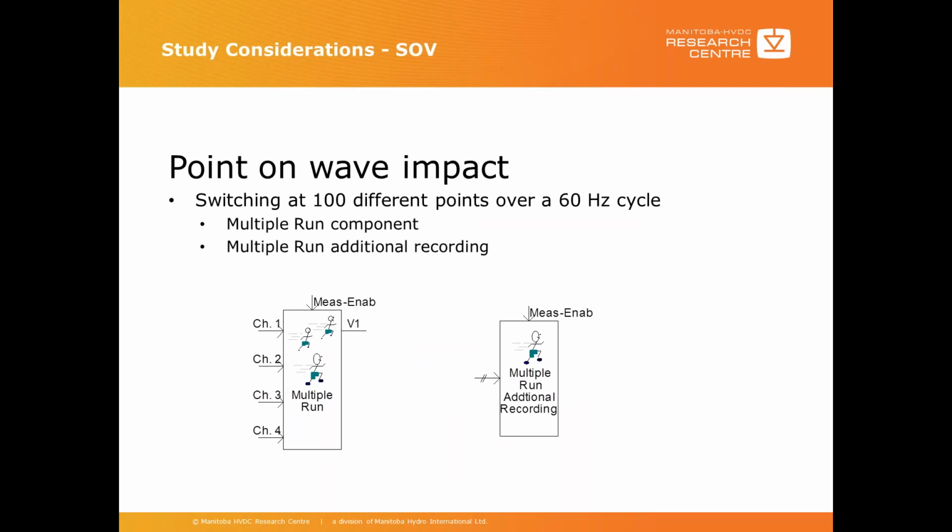PSCAD multiple run component can be used to automate the point-on-wave analysis. The components are shown here. If the number of recording signals are more than what is allowed in the first component, you can use the second component to record more signals.